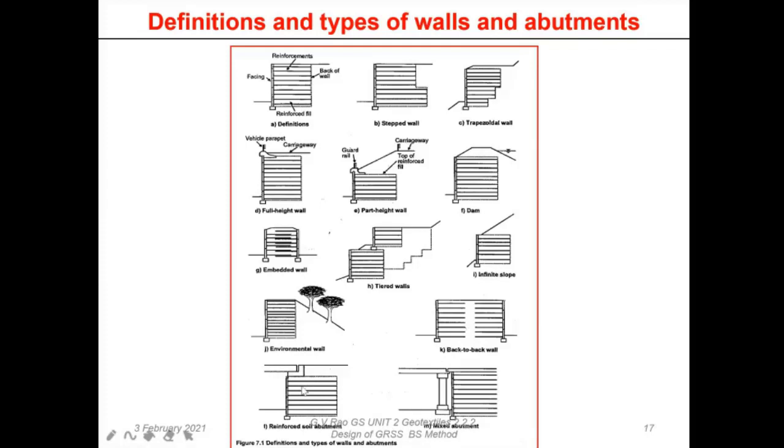The bridge deck is going to rest on the abutment. The other case is, of course, as we have been doing commonly, that the bridge deck rests on a bridge pier. And this is the wall. That means in plan it looks as though we are approaching, so both sides are wall near the abutment. This is what we call closure wall. So approaching this, it looks like this, back to back. And when it is coming near the abutment pier, it is called closure wall.